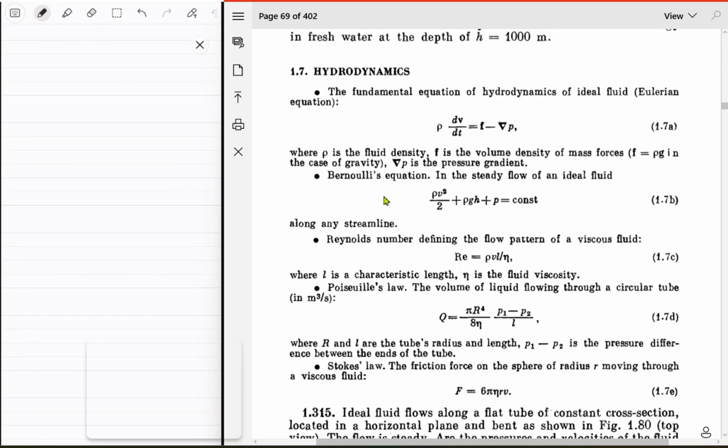Now, there is a condition though that we'll be actually using everywhere. What was I saying? Yeah, this equation only works if the blocks of volume that you're taking, right? So like you have water flowing in that streamline, right? So throughout that streamline, the blocks of water that you're taking, they only have translational motion. They don't have rotational motion. So there might be possibility that along this streamline at some particular point, you have a kind of like a vortex, right? So there's water flowing around it, right?